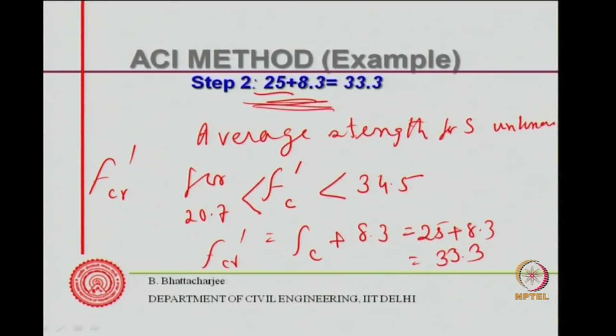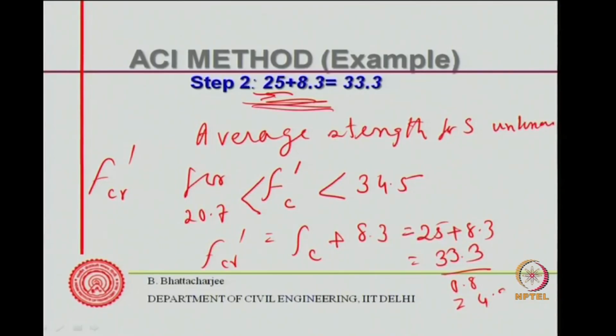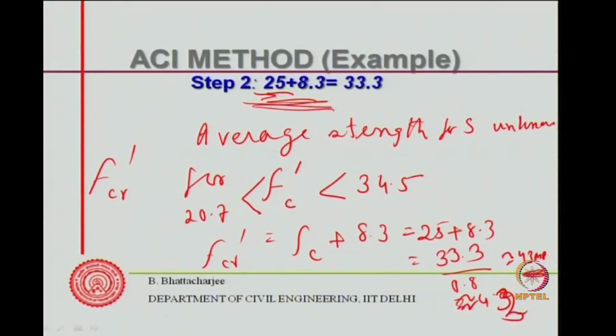And if we compare with the cylinder strength, the average cylinder strength divided by 0.8, I will get roughly about 43 MPa. That would be the cube strength.